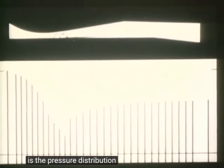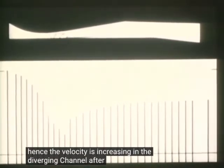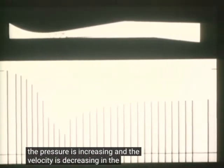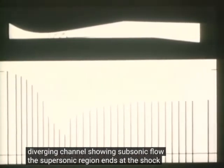So is the pressure distribution, because at first the pressure is decreasing, and hence the velocity is increasing in the diverging channel. After the shock wave, the pressure is increasing, and the velocity is decreasing in the same diverging channel, showing subsonic flow. The supersonic region ends at the shock wave.